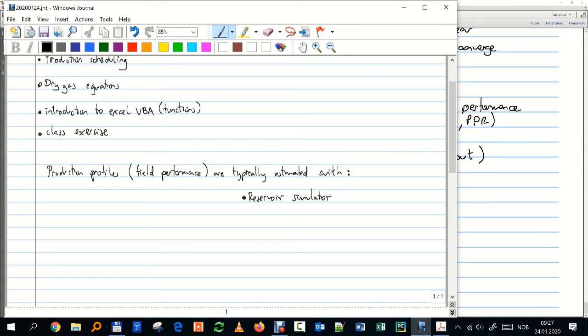You try to represent, which is what a reservoir simulator essentially does. It's a model that tries to make first a 3D representation of my volumes, with all the properties, all the parameters. Then I start to subdivide those volumes. And then I apply conservation equations, some sort of mass conservation equation between each block. Each block has a certain amount of fluid, certain amount of pressure, and then to compute the flow that is transferred between one block and the other, you use some sort of Darcy law, with permeability.